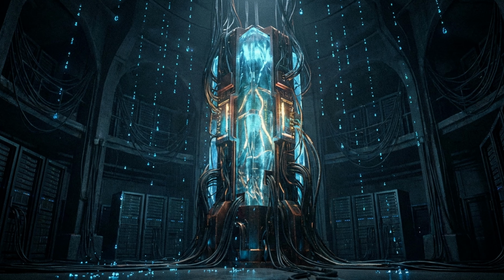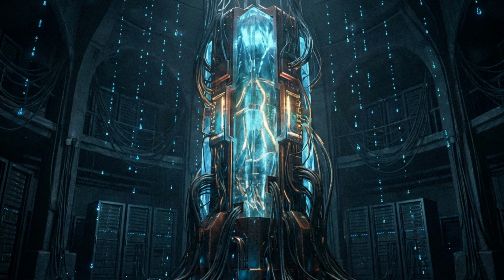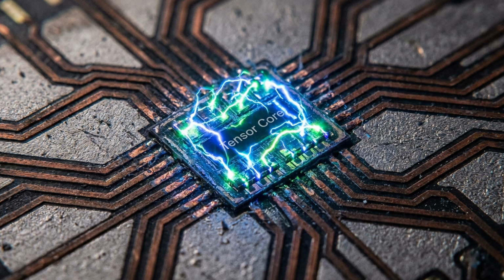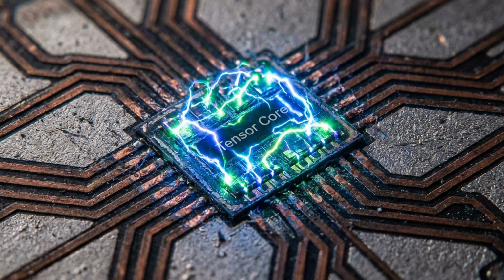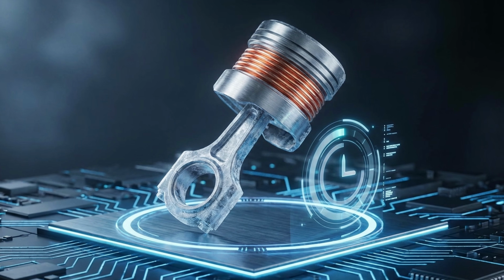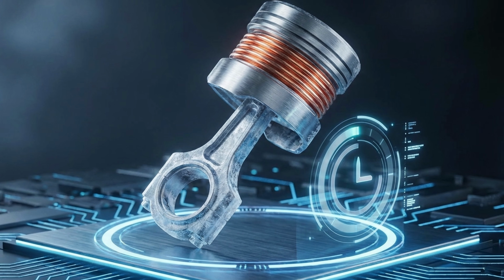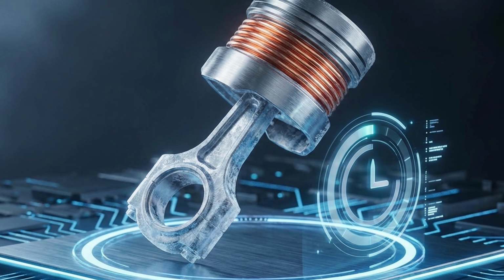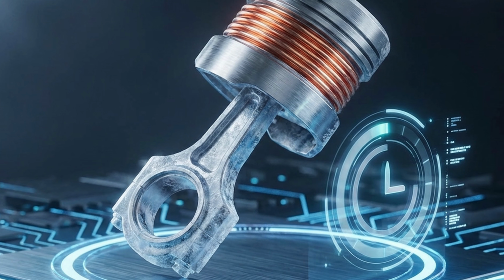This widening discrepancy dictates that modern artificial intelligence workloads are rarely actually compute-bound, they are predominantly memory-bound. Dense matrix multiplications may run in a single clock cycle on a tensor core, but the physical time it takes to move the data from the memory modules across the circuit board to the processor registers starves the system. Operations like batch normalization or simple activation functions feature very low arithmetic intensity. They perform very few mathematical operations per byte of memory accessed, causing the massive computational engines to sit completely idle while waiting for data to arrive.